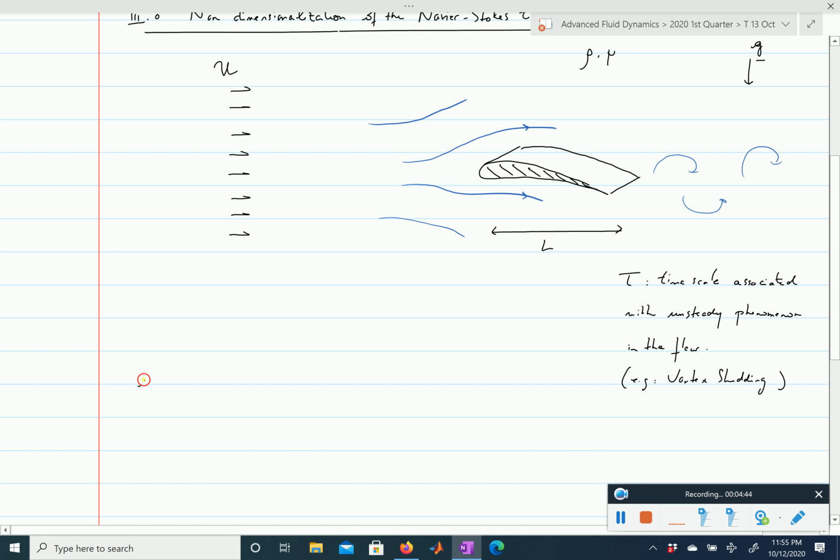So if you're thinking about your velocity vector, u, this is a function of position and time, and you non-dimensionalize it by simply writing u as the product of a vector field, which is now non-dimensional, so this tilde indicates that the quantity is non-dimensional, times, of course, our velocity scale. Note here, this has the right dimension. This is meters per second. This has no dimension, and this is our scale of velocity, which is in meters per second.